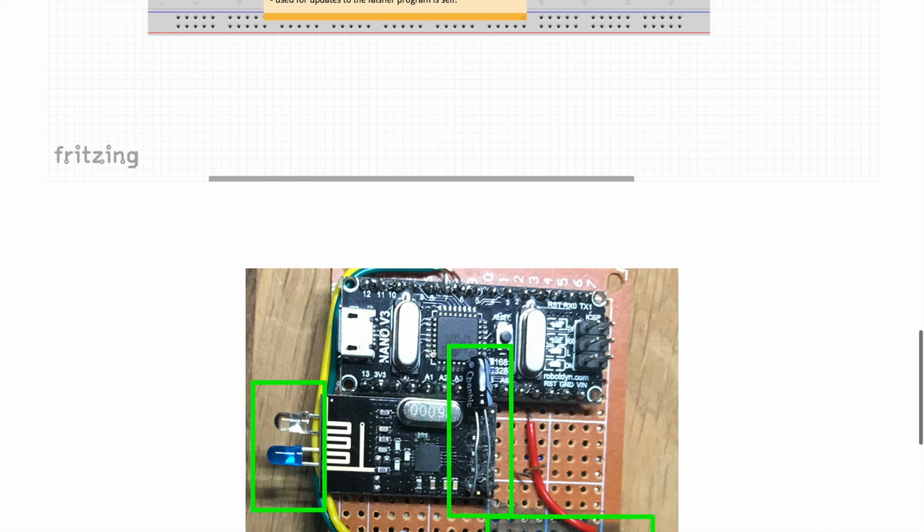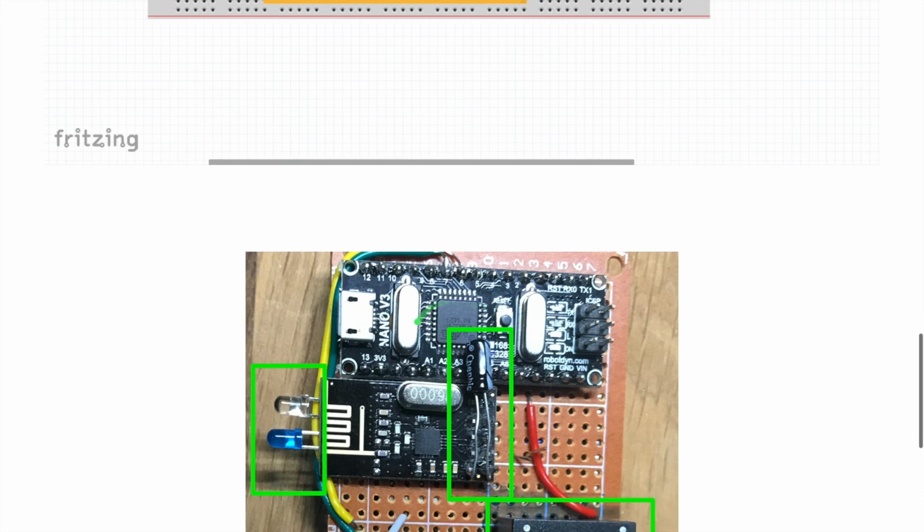You will have to use the same code. And why is that? This chip has a lot of registers and stuff that the bootloader is configuring to send or get the packets. So if the sketch is using a different configuration for this chip, then once it's tweaked, the bootloader will not be able to flash or to use it from the original program.